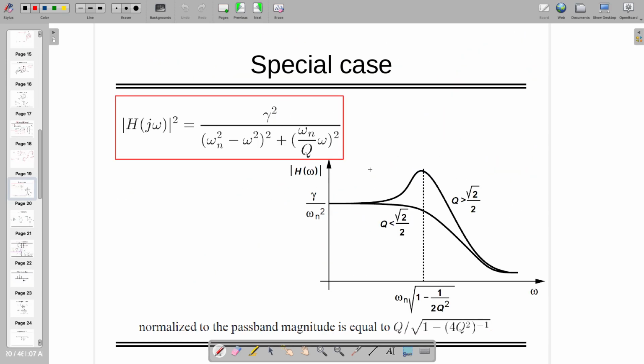Okay, this we already studied in the Bode plot, right? Okay, so we need to look at the place which will give you 1 by root 2, this also gives you 1 by root 2, and this 1 by root 2 is 0.707, or equal to minus 3 dB, and that is why minus 3 dB is a very important number, right? Minus 3 dB frequency, minus 3 dB bandwidth, it's coming from this.